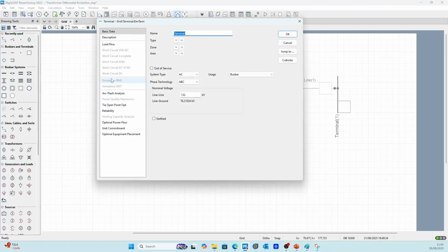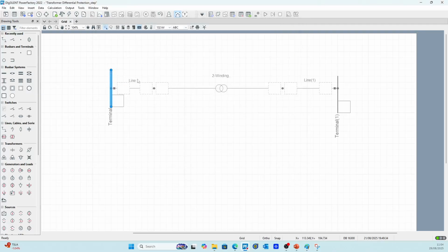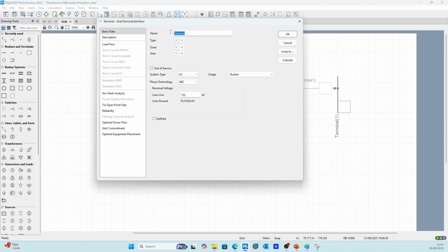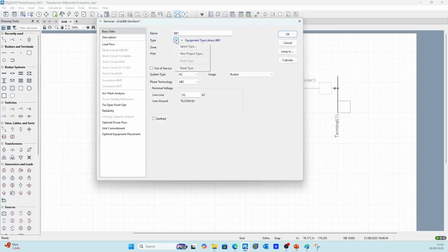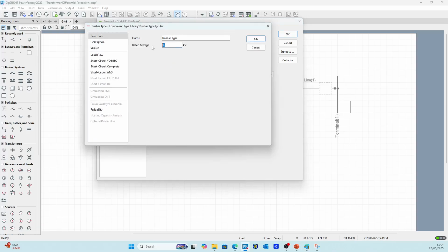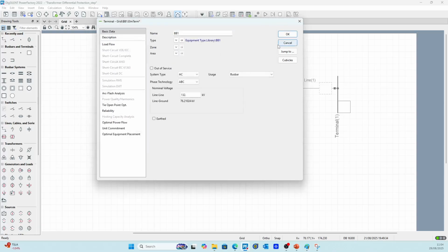So this is the bus bar. Assume now we're going to do a step down transformer. Let's do this one 132 kV. Let's call it bus bar 1. Then I'm going to select this one, bus bar 1 in here, 132 kV. You can create your own if you want from here by a new table, 132 and bus bar 1. Yeah, it's the same.